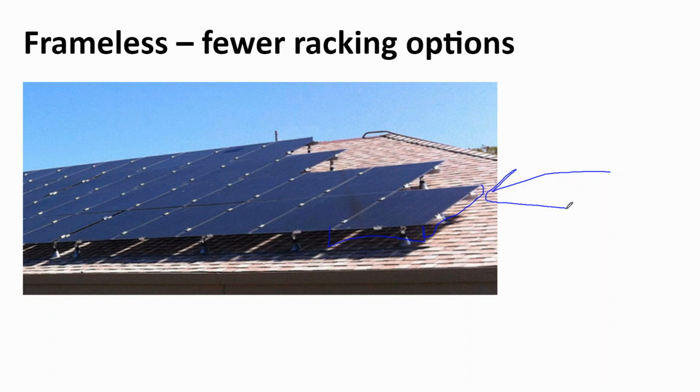But most frameless solar panels have a glass front and a glass back. And the reason why you might want a glass front and a glass back is not like in this case where the customer is just showing off having a thinner framed solar panel. But if you're in an agriculture facility where there's a lot of ammonia gas, or maybe on the coastline if you're afraid about saltwater spray, going with an all glass panel can have some corrosion benefits, insulative benefits. It's very rare though.